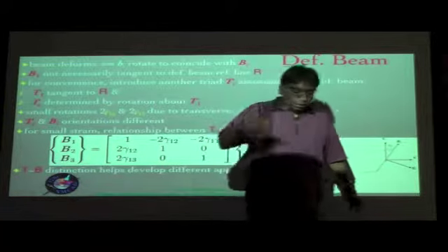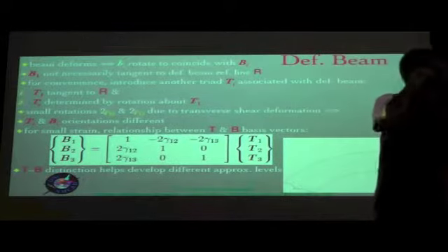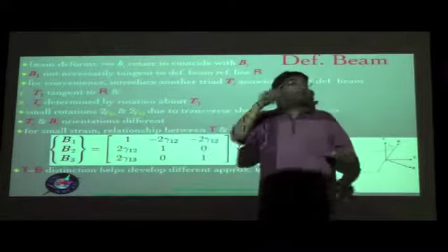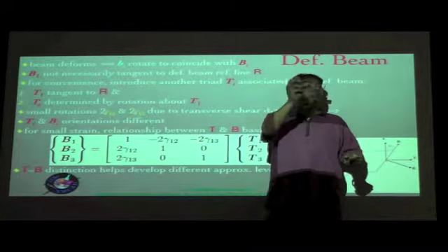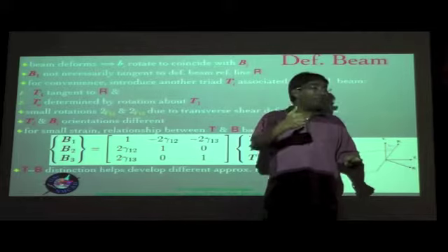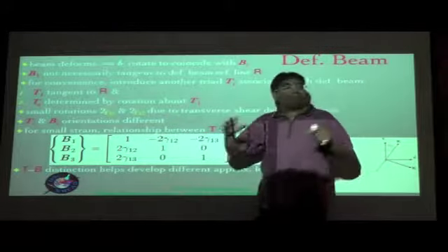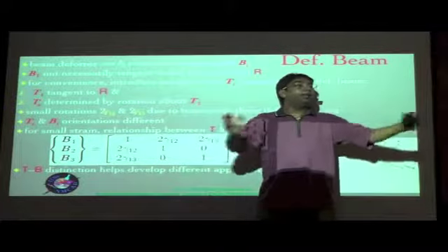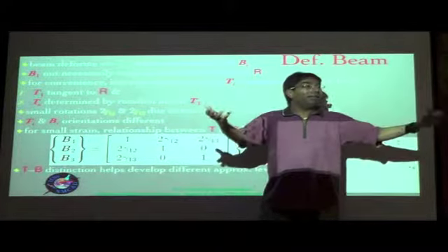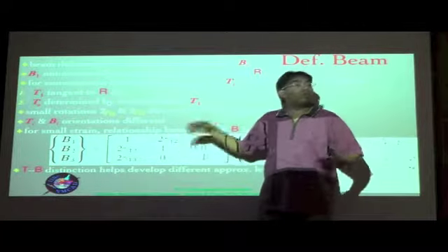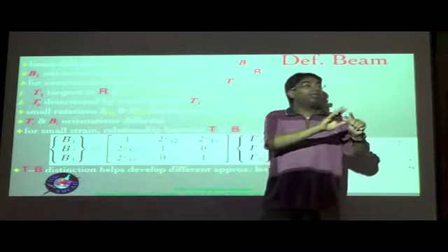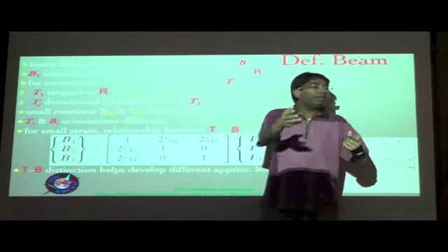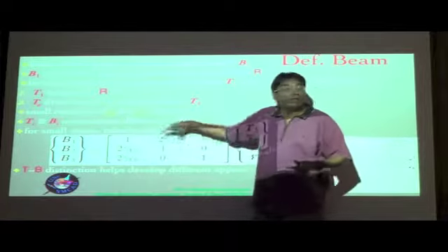Okay. And later on you will also see when we apply the variational asymptotic method that the order of magnitude of this is not even epsilon hat, but epsilon hat times the cross-sectional dimension divided by the length. So which means that the strain typically is of the order of 1%, and then the cross-sectional dimension divided by the length is, let's say, at least 1/10, which basically means that it becomes almost 1,000th. Okay, so therefore there is no harm in taking sine theta as theta itself. So which is how this basically comes.